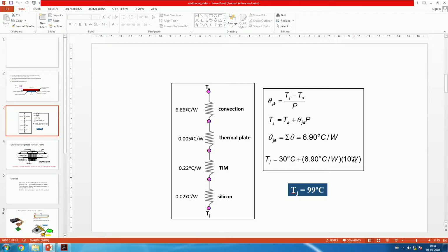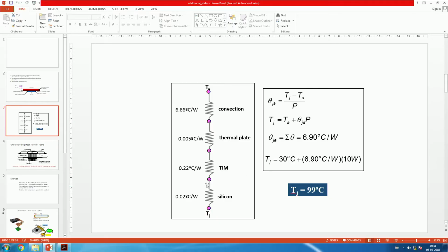Okay. If 8 watts is going up, that means 2 watts is going down. So that means 2 watts might create some issue for the traces or the vias, right? Yes, it is possible. So, I am not even talking of these intermediate temperatures. Now that you know the total Q that is going through, and you know these thermal resistances, you can also calculate these intermediate temperatures. I am not even talking about those.